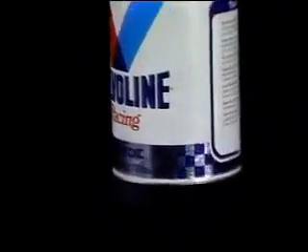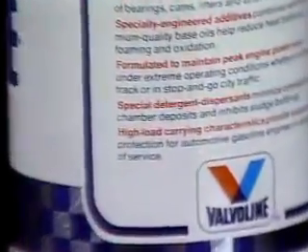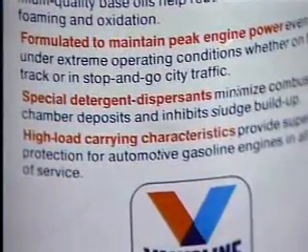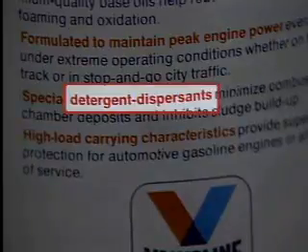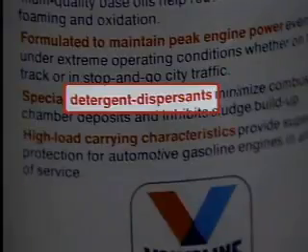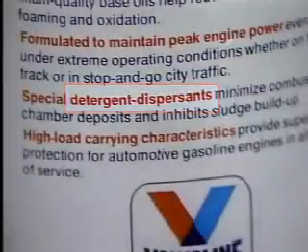And to reduce the formation of carbon deposits and sludge, chemical additives called detergents and dispersants are added to many oils and greases. These additives keep particles in the lubricant suspended so that deposits and sludge don't form. Additives are able to make natural lubricants suitable for many different applications.